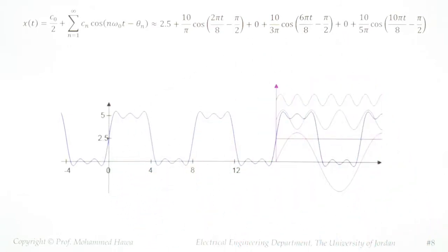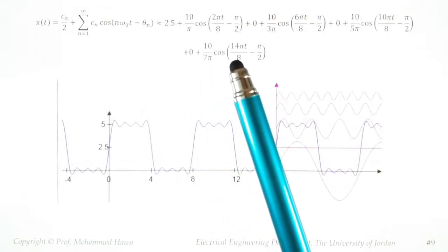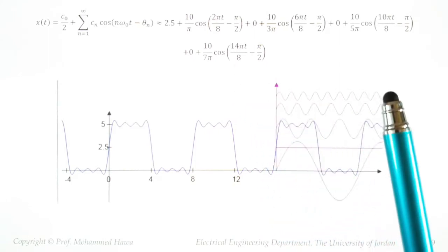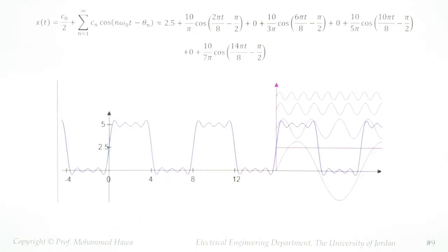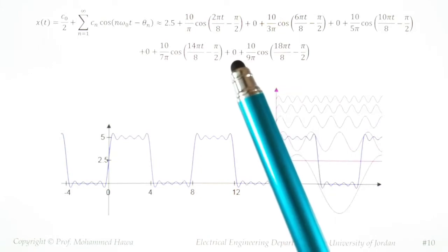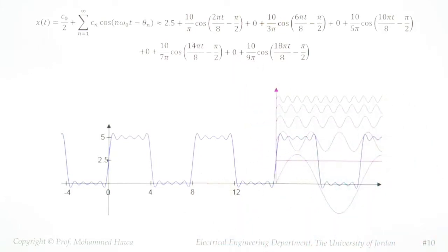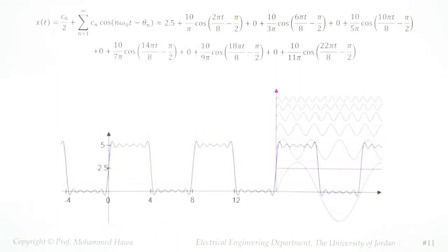Let's add more cosines. Here is another cosine. Here is another cosine, 7 times the fundamental frequency. This is the cosine with even a smaller amplitude. I'm going to add it. This is what I'm getting. 2 more cosines, this one here and this one here. Of course, this is 0, does not affect you, but this one is here. You're getting this shape. If we add 2 more, I'm getting this shape. If you keep adding more cosines, though with different amplitudes and maybe sometimes different phase shifts, what you're getting is a shape closer and closer and closer to the original repeated drift.